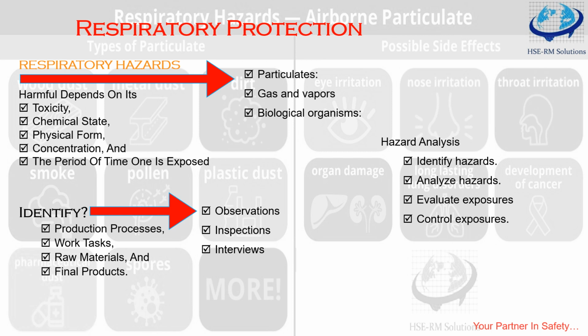Some examples of administrative control related to respiratory protection include requiring employees to use respirators when working with any particulate or any place where exposure is possible, conducting hands-on training on the use of respirators, establishing rules for care, maintenance and repair, and mandating medical examination of all employees who will be using the respirator.